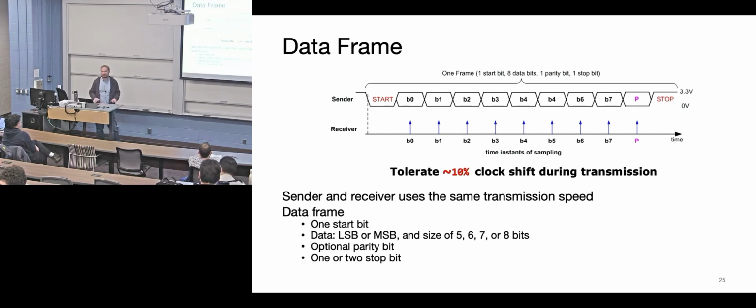There are other mechanisms to do error correction and forward error correction when you talk about communication systems in general. This is just so primitive that we just don't have it quite yet. If you wanted to, you could build it on top. You could send all the messages twice. I mean, that would be one way. But you could send a group of 8 characters, and then the 9th one has some error correction built into it, so that you could do a checksum or something like that to recover a number of bits that got corrupted.